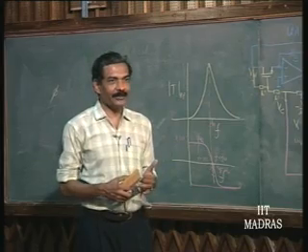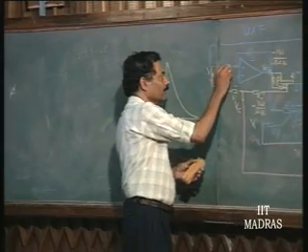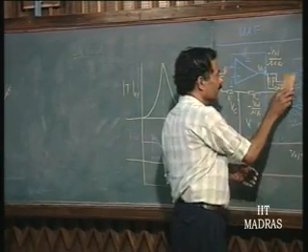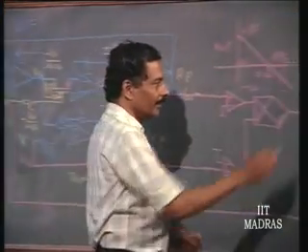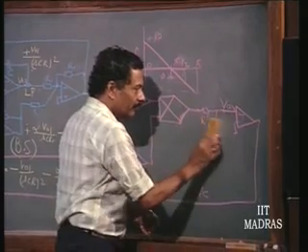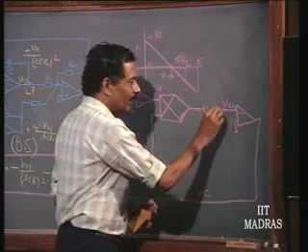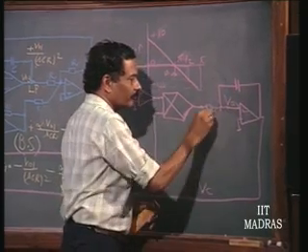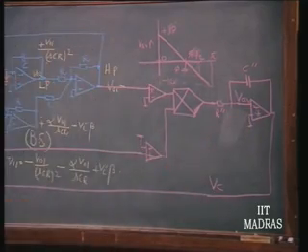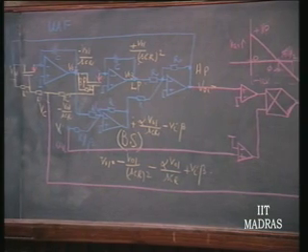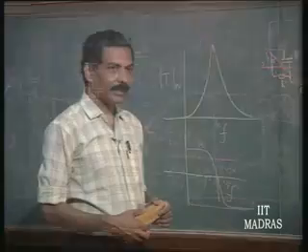In order to make it negative feedback, what should we do? We can change any one of the things. I would like to change this rather than anything else. Instead of n channel, I make it p channel and retain this as minus, because I would like to not use large capacitors here. Instead, I would like to use the Miller effect and make this an integrator. So, this is what is called a self-tuned filter, which is now going to work satisfactorily.